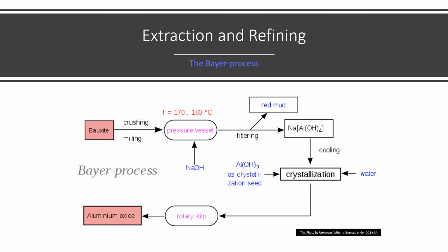The production of aluminum from bauxite is a two-step process: refining the bauxite to obtain alumina, and smelting alumina to produce aluminum. Bauxite contains a number of impurities including iron oxide, silica, and titania. If these impurities are not removed during the refining, they will alloy with and contaminate the metal during the smelting process. The ore, therefore, must be treated to eliminate these impurities.